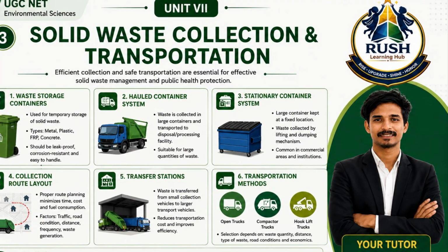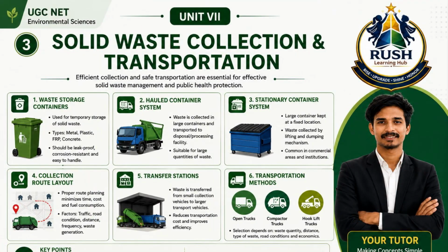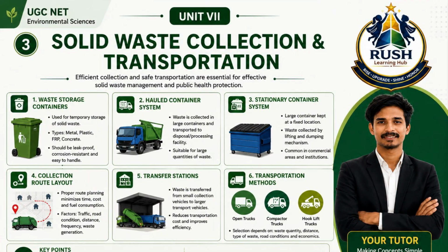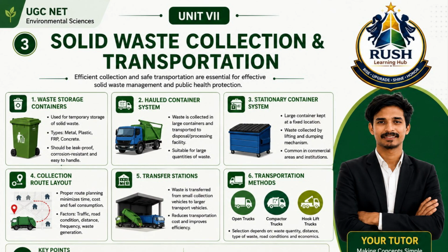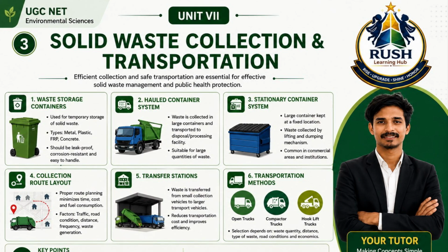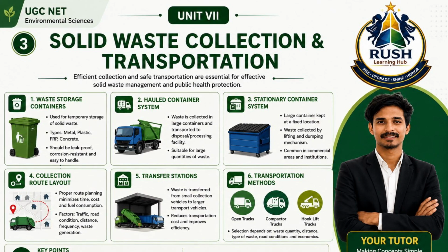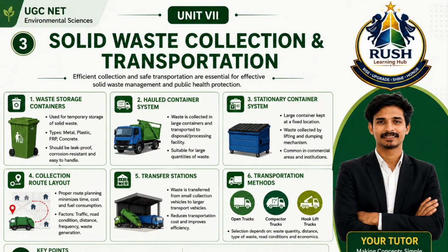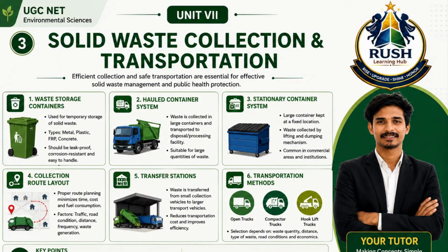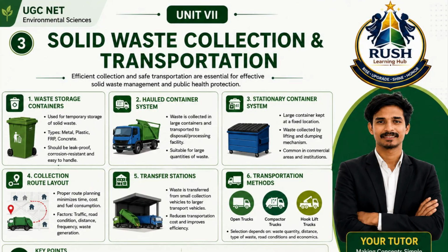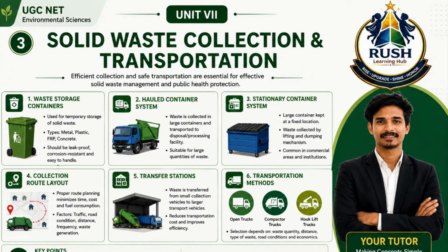Next, let us discuss transfer stations. A transfer station is an intermediate facility where waste collected by small collection vehicles is temporarily unloaded and transferred into larger transport vehicles. Instead of every small collection vehicle traveling long distances to a landfill or treatment plant, waste is first brought to a transfer station.